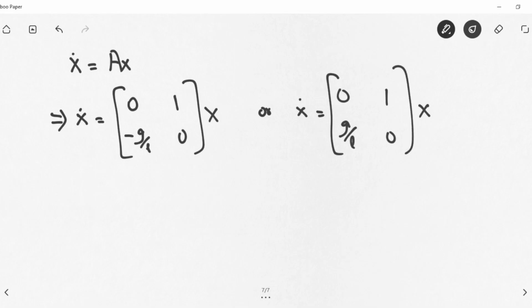So now you have obtained a linear model, but because of multiple equilibrium points for this nonlinear system, you are getting multiple linear models as well. It's not going to be a straightforward case, because from these two models we will get different sets of eigenvalues, and one set of eigenvalues may say this system is stable, another set may say this system is unstable. It can do that. So this actually represents the behavior of the actual nonlinear system.